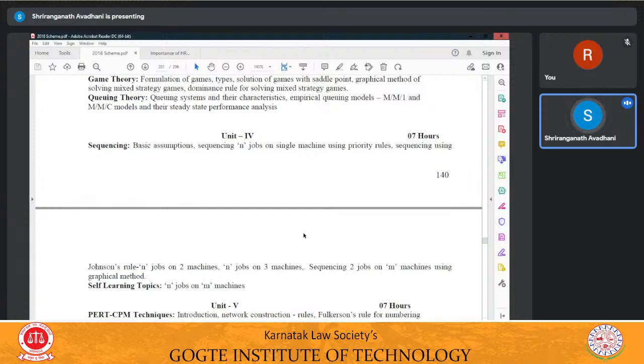Then the second type is n jobs on 2 machines, where we'll be using Johnson's rule to get the optimum sequence. And again, after getting the optimum sequence, we'll be calculating the total time required to complete all the jobs on these 2 machines. Also, the total idle time that is required to be calculated on each machine. Then extending the types to n jobs on 3 machines. So it is an extension of n jobs on 2 machines. We'll be converting the given 3 machines problem into a 2 machines problem, again by using certain rules and conditions. And then again the unknowns are the total elapsed time and idle times of machines that we are going to calculate.